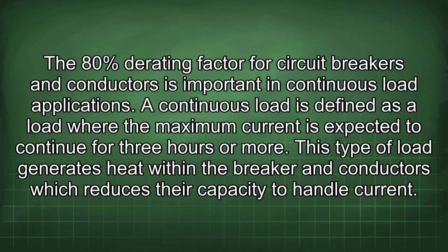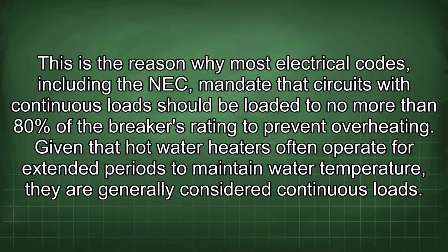The 80% derating factor for circuit breakers and conductors is important in continuous load applications. A continuous load is defined as a load where the maximum current is expected to continue for 3 hours or more. This type of load generates heat within the breaker and conductors, which reduces their capacity to handle current. This is the reason why most electrical codes, including the NEC, mandate that circuits with continuous loads should be loaded to no more than 80% of the breaker's rating to prevent overheating.